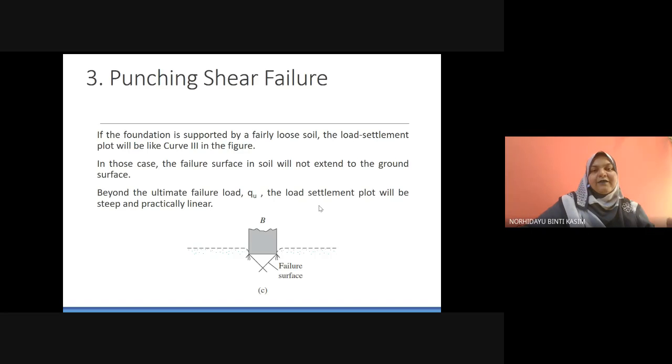We worry that if it goes beyond the ultimate bearing capacity, punching shear will occur. We don't want the column punching through the slab, so you have to check and make sure it passes.